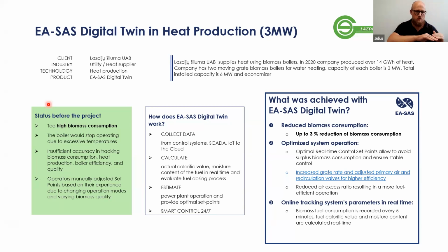So the temperature goes up and then it crashes down, and then you need to put in more fuel, more air, you need to play with the control system in order to stabilize the process. It's okay if once you crash, you get back. But what happens if it's two or three times? You waste a lot of fuel, and there is no stability in the process.